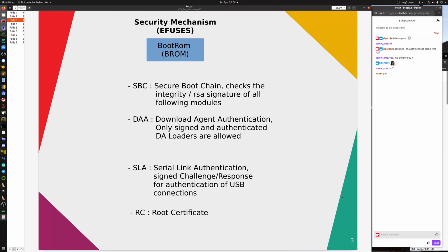And what's not on that slide is that you've got even more, which, for example, for the newer MTKs, you've got memory read, memory write protection, or EA command protection, and remote protection. Because for the newest MTKs, if you use the SP Flash Tool, it's going to remotely connect to the server. It's going to ask, is that guy allowed to do any flash interaction with that device? And if it says yes, then you can continue. So that's also another security mechanism.